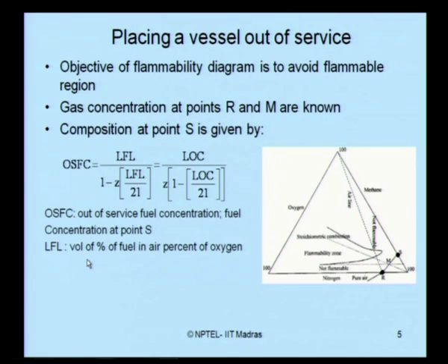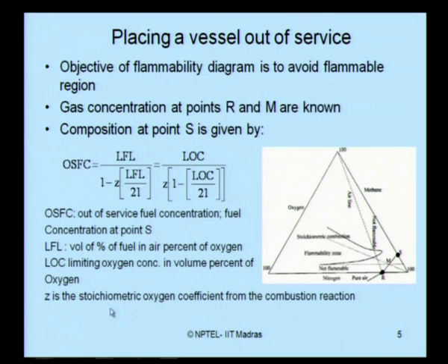LFL is volume percentage of fuel in air, percent of oxygen. LOC is what we understand as limiting oxygen concentration expressed in volume percentage of oxygen, and Z is the stoichiometric oxygen coefficient for the given combustion reaction. So, once I know all these values, I substitute either in this equation or in this equation accordingly to get my vessel out of service fuel concentration. So, I can easily locate the point S and see whether the point S is going to be in the flammable region or not.